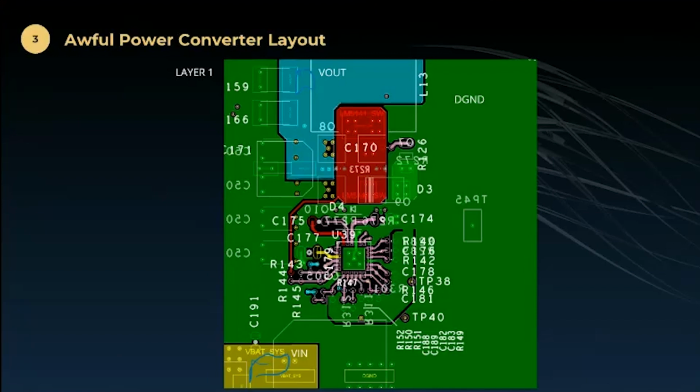And what we see from that, this is layer one, which is actually not the side where the circuitry is. I'm not sure why, in this case, it was on the bottom of the board. You shouldn't let that switching node come to the opposite side of the board, but they did in this particular design. And you'll see that it is right next to the V out. So they've got a node there. It's not that they didn't keep the size small.